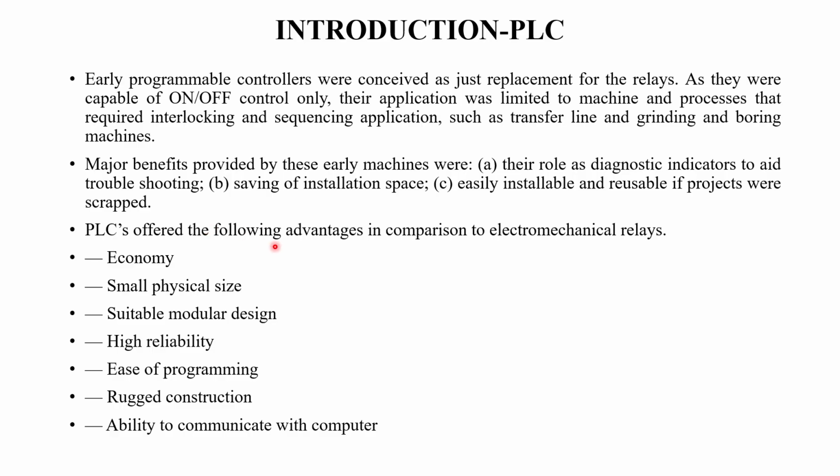Whereas a PLC offers advantages in comparison to the electromechanical relay: economy, smaller size, suitable modular design, higher reliability, ease of programming, rugged construction, and ability to communicate with the computer. These are the benefits of introducing a PLC over electromechanical relays.